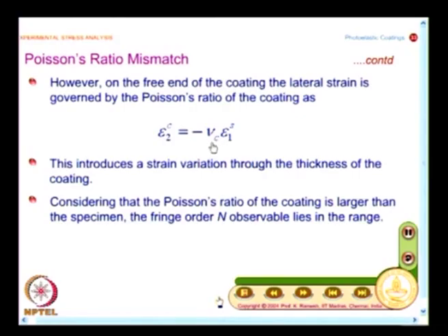See, we saw in the case of coating applied to bending problems or torsion problems, the strain variation in the coating was seen mainly because of the way the model or the prototype was loaded, you had a strain variation, that is acceptable.